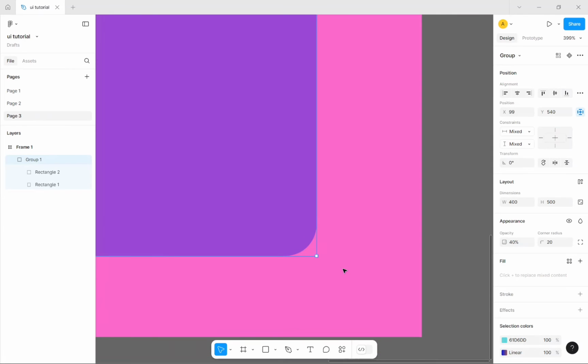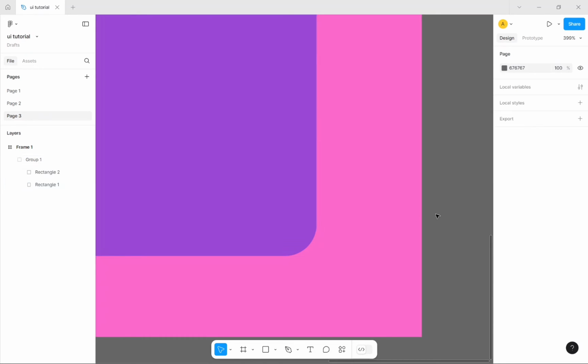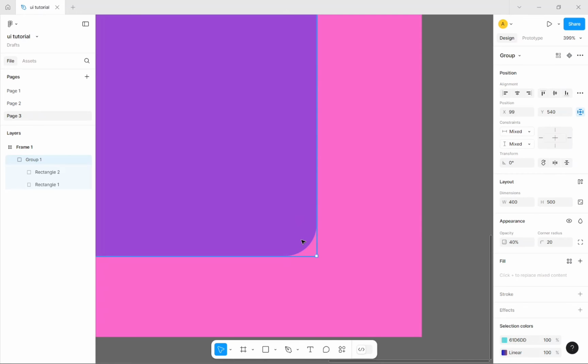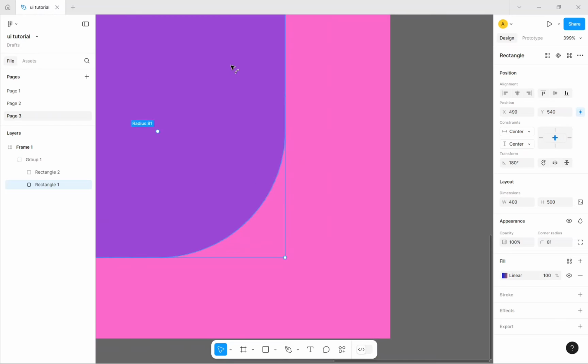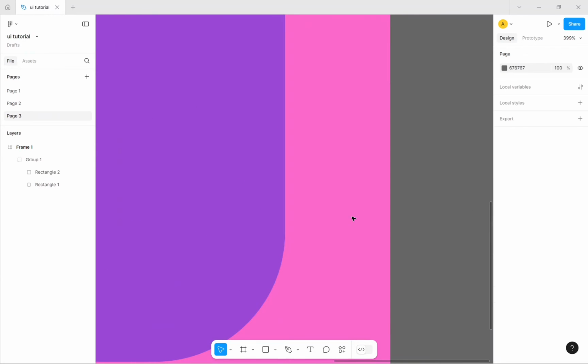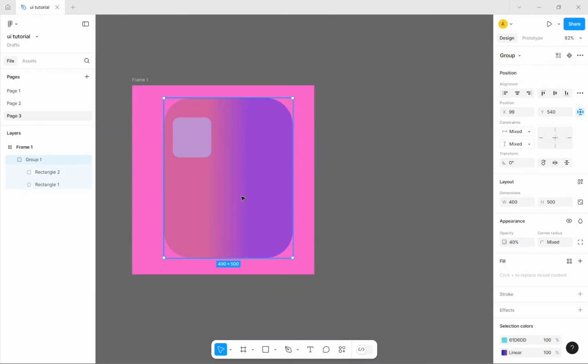Imagine you want to use your eyes as a guidance with the mouse. So what you do, you click on the rectangle, then at the corner you double click, see you have a radius option. So you can drag this, and see your whole radius is being changed. Okay, let's say you do not want to change every radius, so what you do, you would, right now what it's doing, it's changing every radius, right?